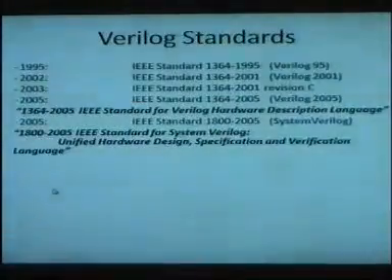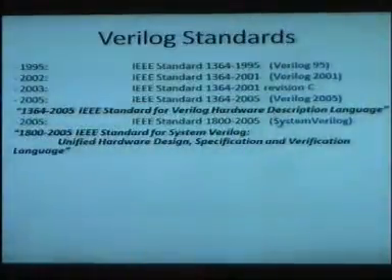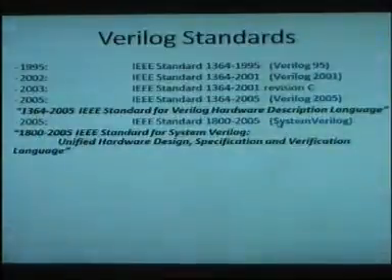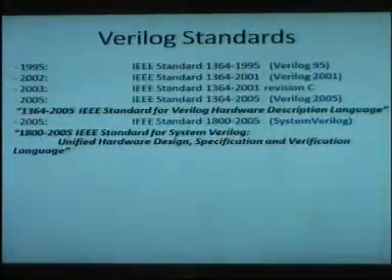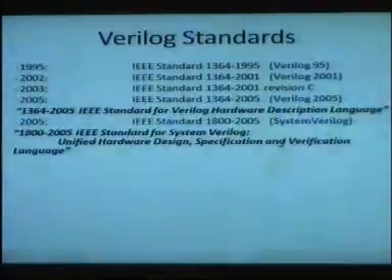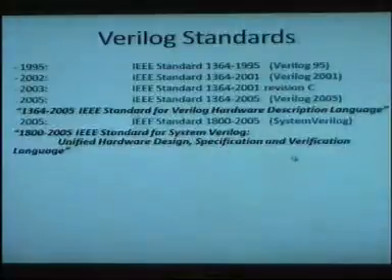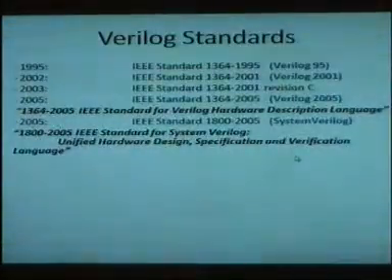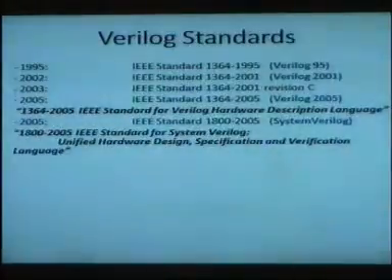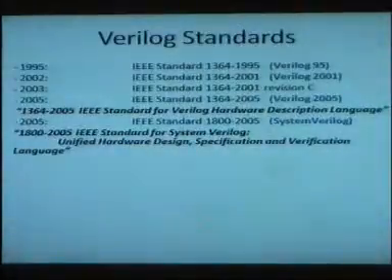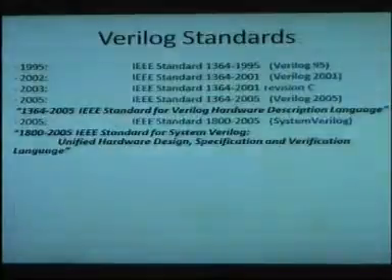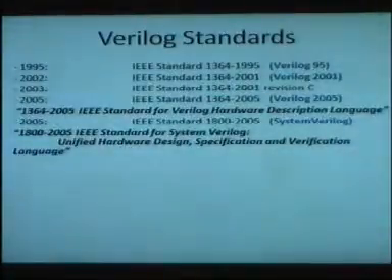So the industry decided to sit down and define another standard of Verilog, which is called System Verilog. The problem with System Verilog, it's not a problem, it's the power of System Verilog, is that it is for hardware design, specification and verification. They mix everything in one language, and that is what makes it very, very complex to learn and very complex to use. And no synthesis tool usually at this point supports System Verilog. For example, Xilinx will not support System Verilog.